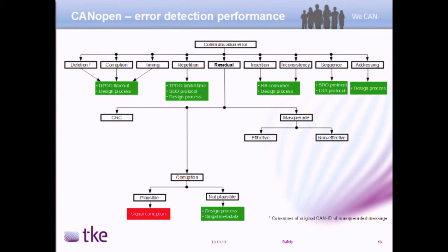And then the masquerade failures. Because in typical control systems, we are using a very small subset of the available ID space, the majority of the probability gives no effect, because the target CAN ID is not in use. But if we get a match, the CAN ID is transformed to another CAN ID which is in use.